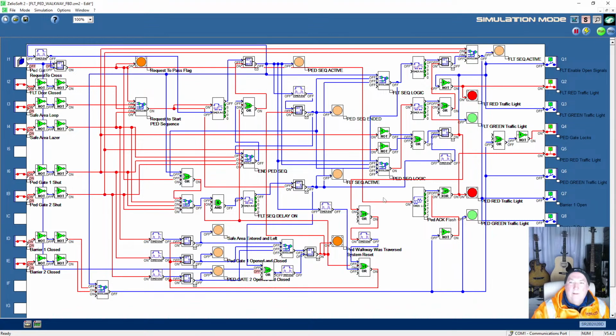It'll count back down, and will it switch to FLT? No. It can't switch to FLT because, what is the reason? Because we've got a permanent output here. So we've got an OR on the pulse, and we need one more line to it by the looks of it. So we've got a flag set up there.